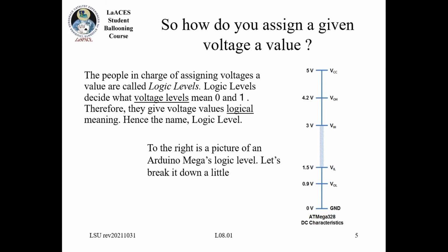Yes, I have a question in the room. What is the space between 1.5? So I was just asked basically, what is the space in between the 3 and 1.5 volts? And that is basically what you would call indeterminate. Nothing that is involved in the digital logic of this should ever output a signal in that range.